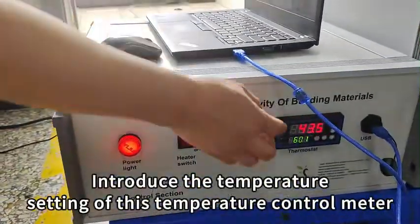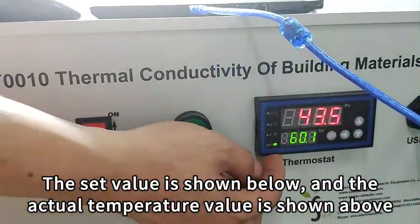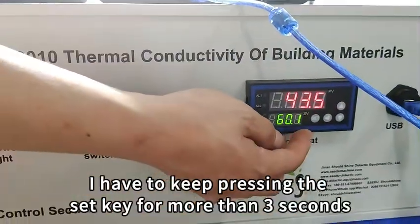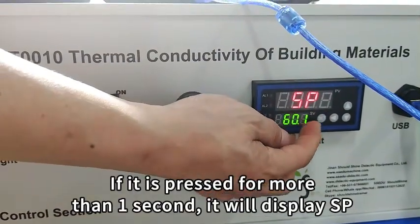Introduce the temperature setting of this temperature control meter. The set value is shown below and the actual temperature value is shown above. I have set it to 60 degrees now. If I want to set it to 65 degrees according to the experiment, I have to keep pressing the set key for more than 3 seconds. If it is pressed for more than 1 second, it will display SP.